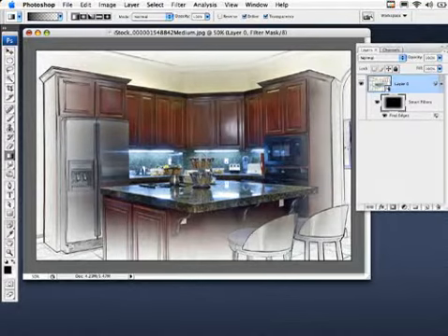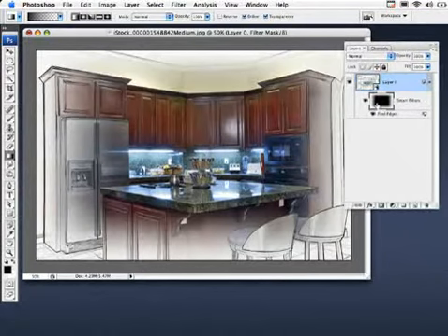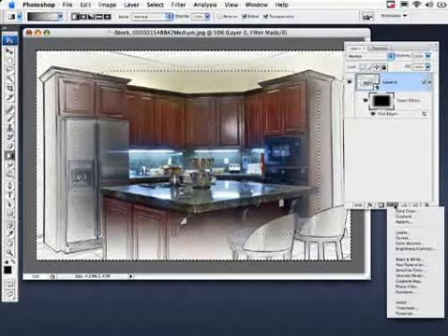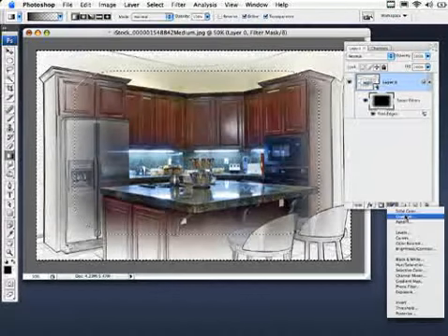Well, the outlines still are retaining some color artifacts in there, so I'm going to load that layer mask as a selection. And of course, if you know about alpha channels, when you load an alpha channel as a selection, all the white and gray areas will be selected areas, and black will be unselected altogether. So I'm going to hold down my Command or Control key and click right on that layer mask. It will load it as a selection. Then I'm going to go under the adjustment menu here, and we're going to go to set.